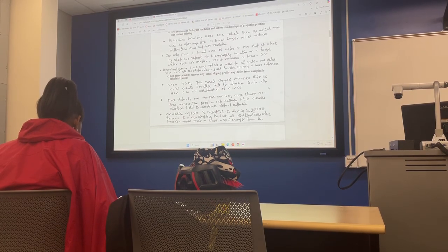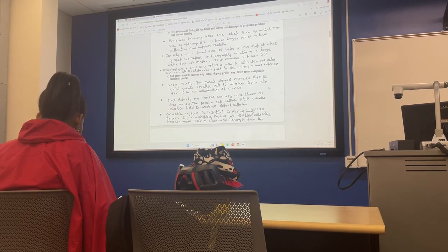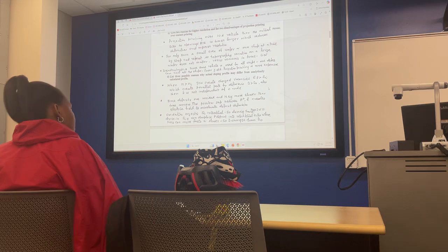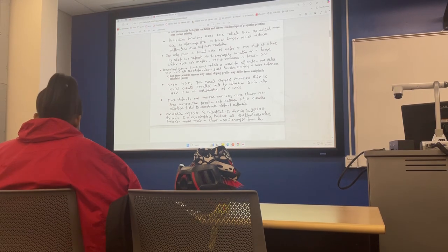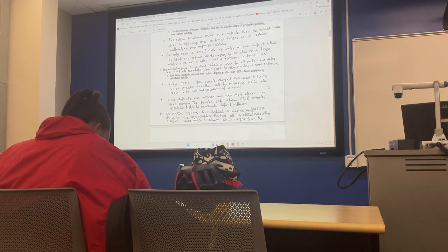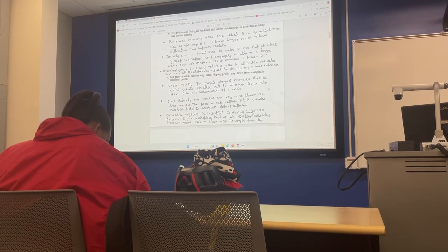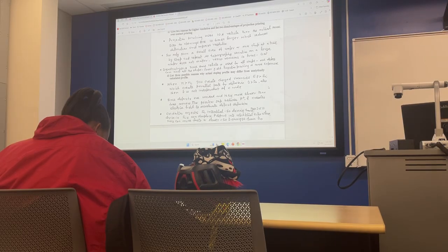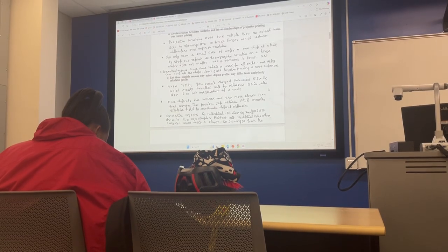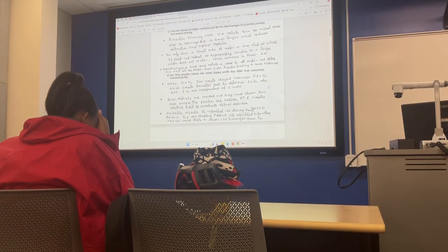The question is why you're analytically calculating where D is constant, but there are 3-4 things that can change the D that you are using in the equation. So that was question 1. So basically simple answers were there. In projection printing, basically because you are using a 10x reticle and scanning a small area, those are the reasons why it has better resolution, correct?